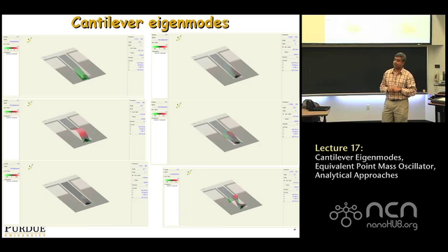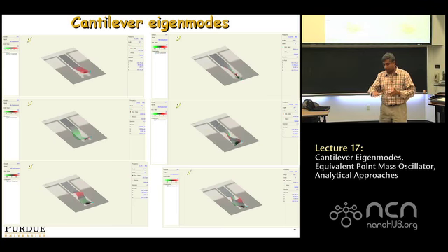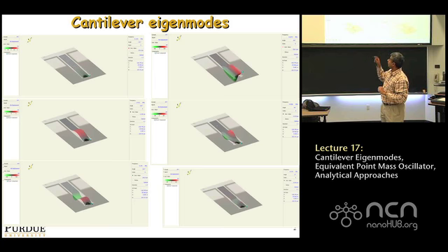How this is done is you take your cantilever chip and shake it with a piezo, but observe it under what's called a laser Doppler vibrometer, which makes a grid of points on the cantilever and scans the vibration response at every point of the whole thing, so you get full-field information of displacement. The colors are proportional to the actual displacement at that point, so it animates basically at those frequencies.